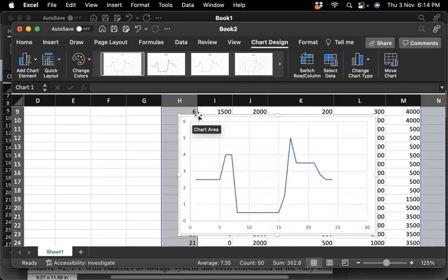Of course, here you can take some decisions. So, for example, whenever you are considering a PV system, you have to consider that in this case you have what we call night loads. So you have to have a solution for these night loads, either using grid, if it's a PV grid connected system, or maybe using a backup source like a diesel, or you have an alternative storage bank in terms of batteries that can supply the load at night. Of course, we are going to do this in more details while we are going through the different sizing process in our course. But this should be considered, of course. But what you see here, my dear students, is simply what we call a daily load profile.